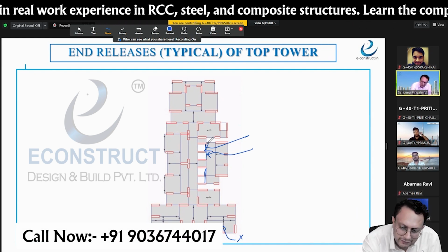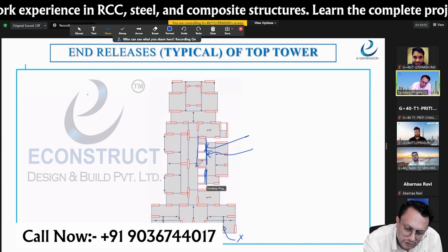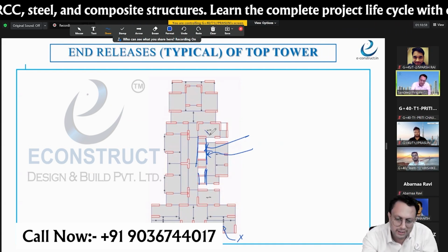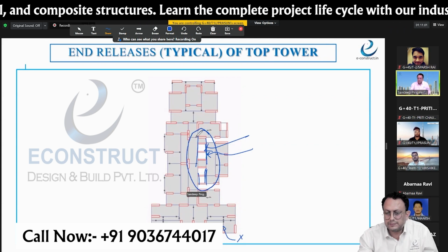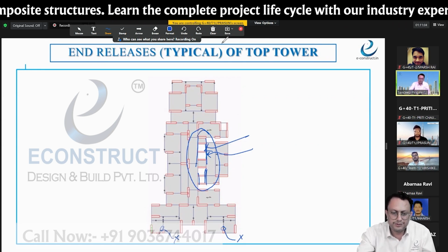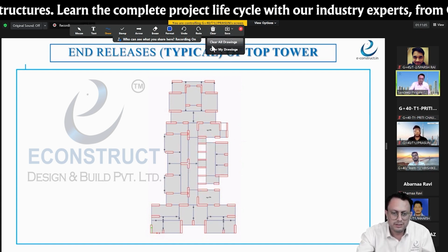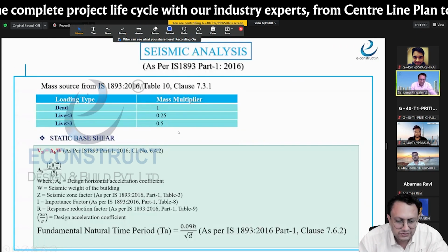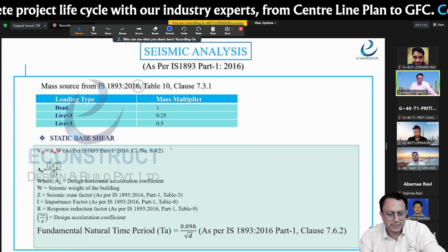Or maybe if you are giving the shear wall here, give the wall here with the opening, so it will be satisfied. So the central stiffness would be higher, because you guys are facing problem in the deflection, no? That's why.